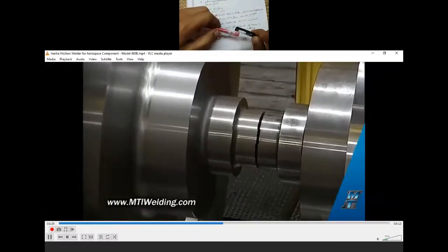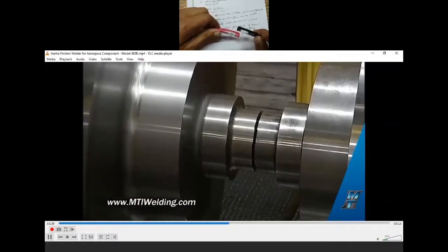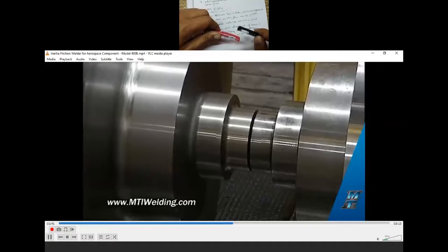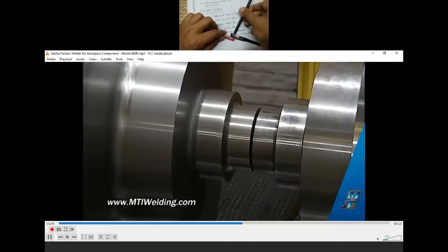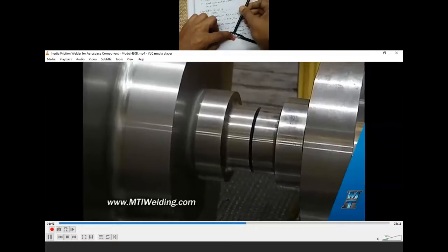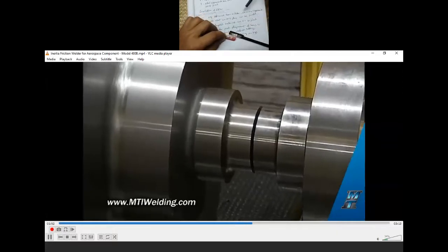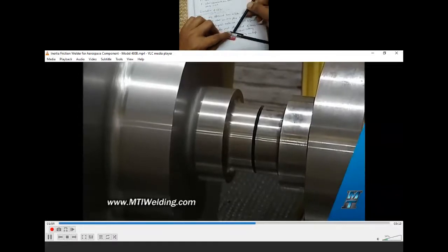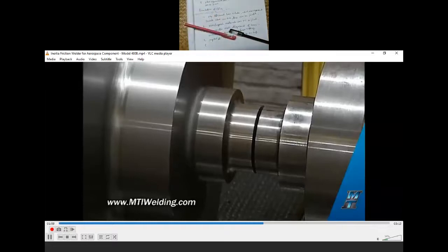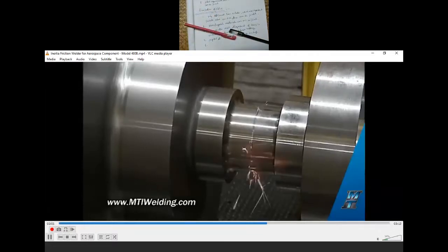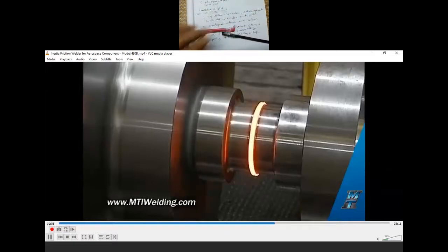You turn one job, rubbing occurs, the material gets heated, now you stop it, and then you must have a mechanism so that you can apply pressure like this, at a perpendicular axis, then you can do it. So with this other device, you must apply pressure so that this joint gets enough pressure to get joined, and then you can join it, which is very difficult. But if you apply a grip like this, it is possible.